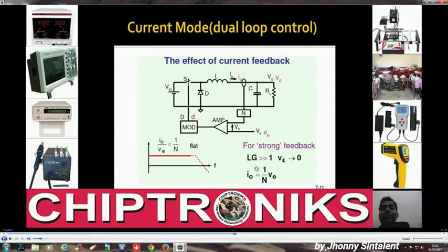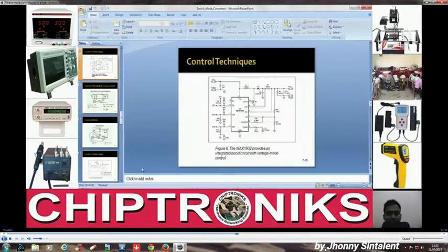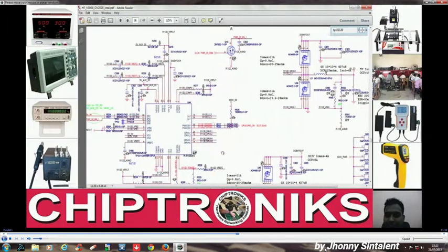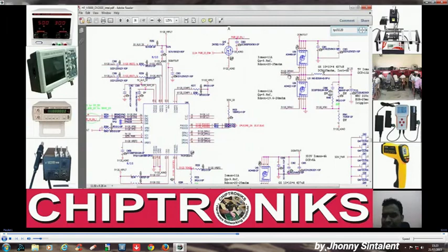And how do we control current? We sense the output current. And that sensed output current is compared with an internal comparator, this current and V error, and that error will try to drive internal PWM, pulse width modulation, and that will produce the gate drive signal, that is drive high and drive low, over here you see, drive high and drive low.